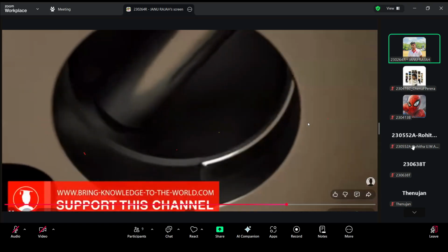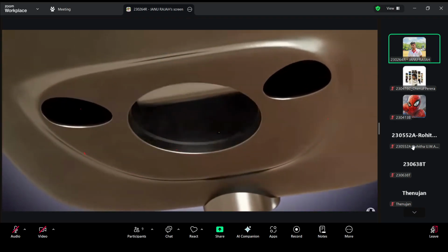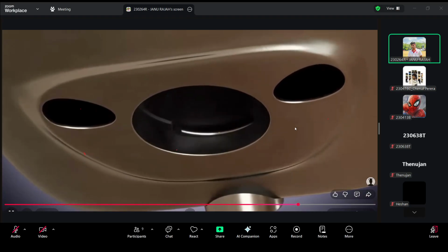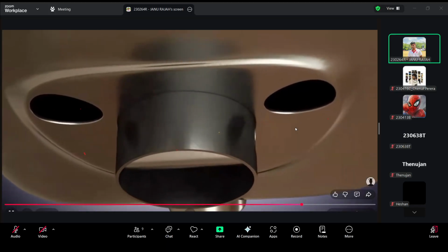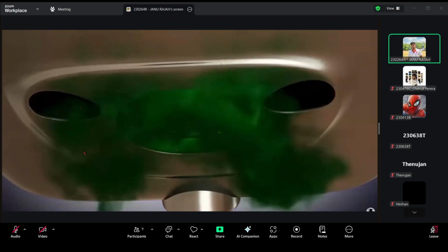The piston, moving up and down in the cylinder, opens and closes the inlet port consistently. Here the transfer port and the exhaust port are opened and closed by the piston itself. But in four-stroke engines, we are using separate valves for that. When the inlet port is open, the mixture is able to flow in. The mixture is then forced into the transfer ports by the piston.